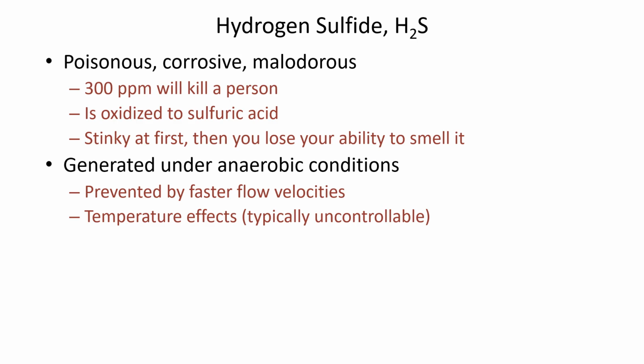And so there are things that hydraulic designers can do to try and prevent anaerobic conditions and hydrogen sulfide from forming. For example, if your pipe is too big, like if you've exaggerated your demand estimation, then most of the time the water's going to flow very shallow in that pipe. Usually we think of oversized pipes as being good because we're providing plenty of capacity.